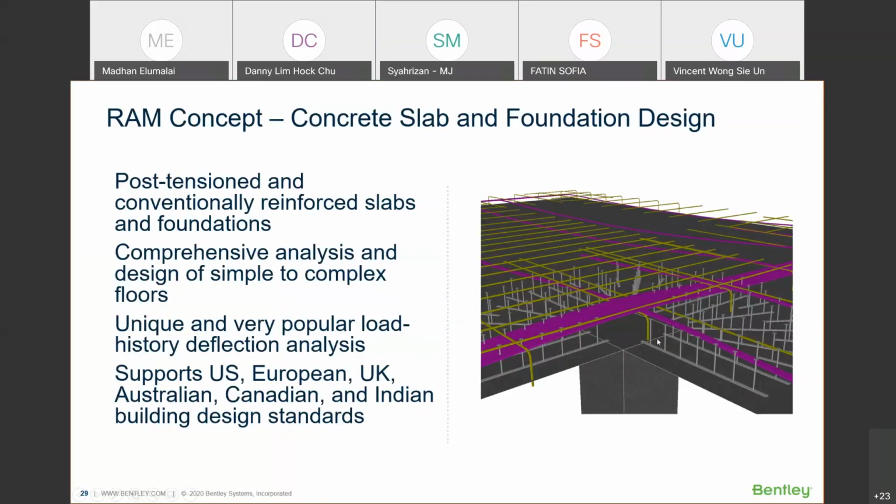What is the advantage of flat slabs? Because there is no beam, you get more headroom for the floor, and also you save material because there are no beams. It's just the slabs and the column drops that help withstand the load from the floor. So for Malaysia, it's a good market to use flat slabs. And when flat slabs are designed, punching shear is a more important criterion for the design. And this program's strength lies there. It's very good in punching shear design.